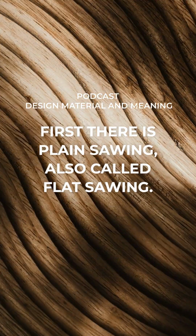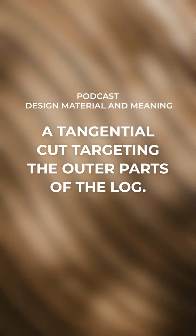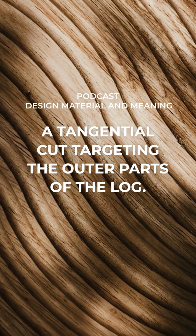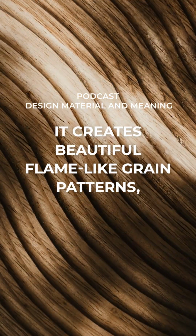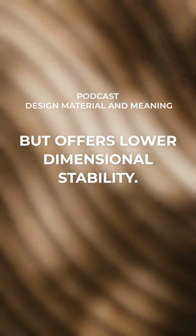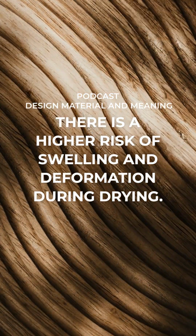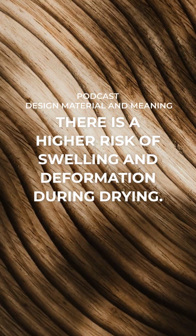First, there is plain sawing, also called flat sawing, a tangential cut targeting the outer parts of the log. It creates a beautiful flame-like grain pattern, but offers lower dimensional stability. There is a higher risk of swelling and deformation during drying.